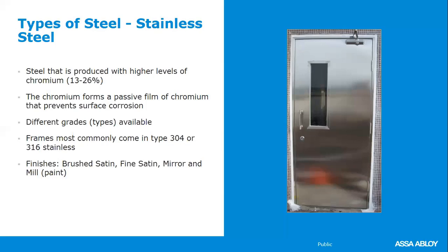Chemical storage areas, where there's a lot of water. Say you have a project that is a food processing plant. That is one place where you definitely don't want to worry about anything adhering to the material, so you'll see that called for as stainless steel a lot of times. Where you have a lab where they're hosing down that room every night, you will see those openings specified as stainless steel. And then you drill down a little bit more and you get into 304 versus 316 stainless.